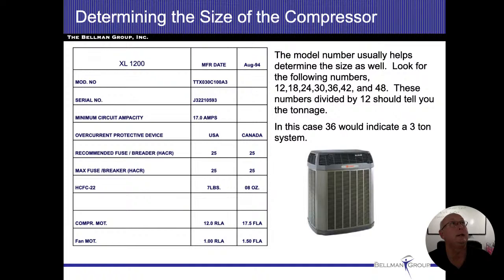All right, so off of this data plate, we know our maximum breaker. We know the wire size that it should be. We know how big our system is, and we're able to determine how old our system is too.